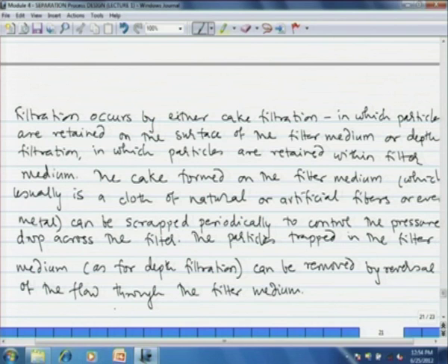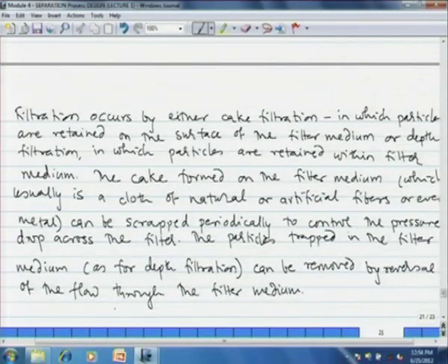However, nowadays, since membrane modules are available for gas separation, you can install another separation process, a gas separation process, so that selectively methane is purged and hydrogen is recycled. If you use a general recycle purge stream, then along with methane some hydrogen also gets purged, but by application of a membrane module at the purge stream, you can selectively filter out hydrogen and recycle it to the reactor.